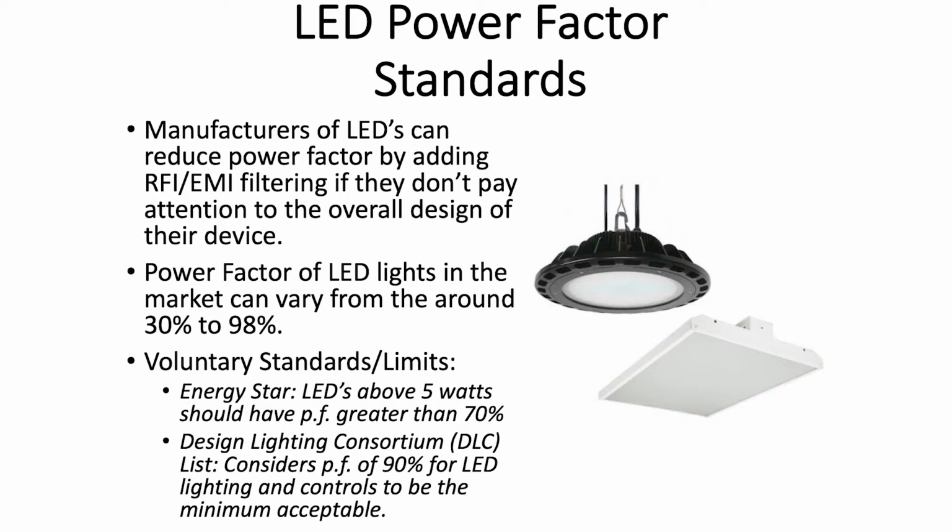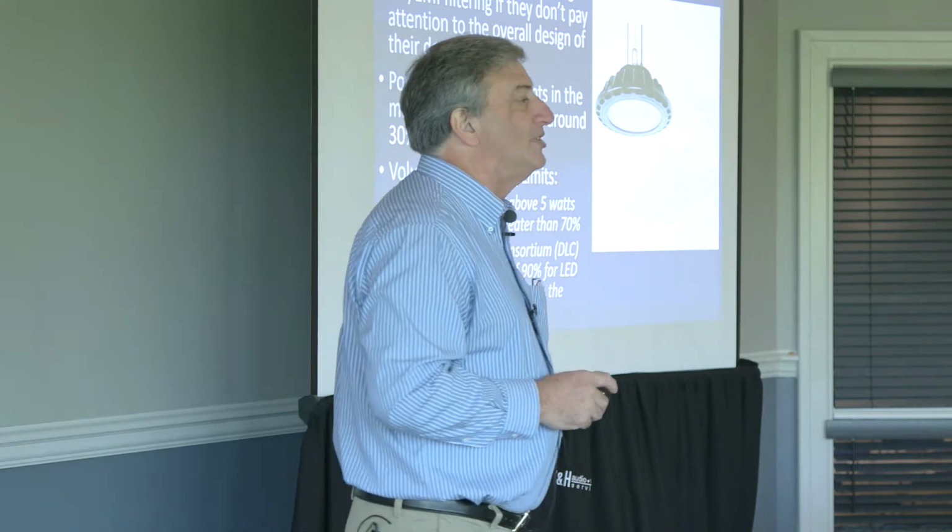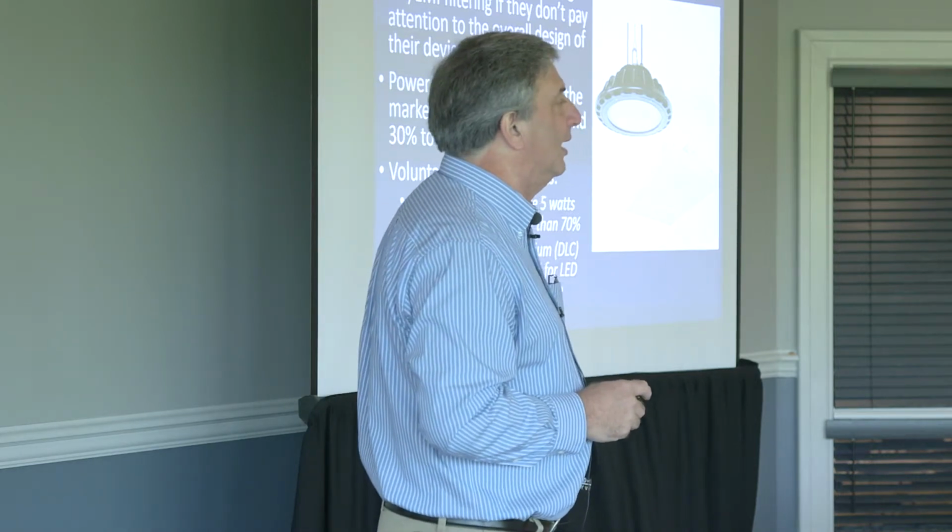So manufacturers of LEDs can reduce power factor by adding RFI and EMI filtering if they don't pay attention to the overall design of their device. What we've seen happen is LEDs generally, when they first were starting to be commercially available, were pretty good at power factor. Then they had a lot of complaints about my LEDs producing a lot of noise and messing up wireless signal systems in my facility, in my plant or building.